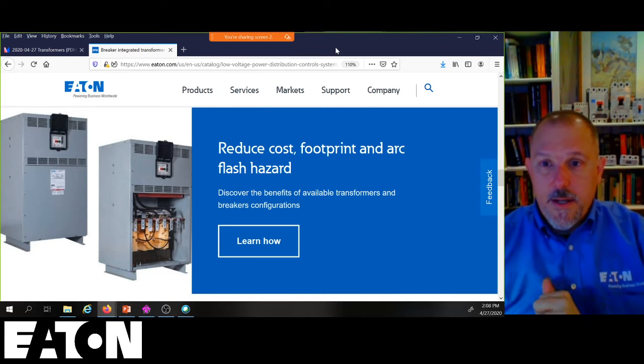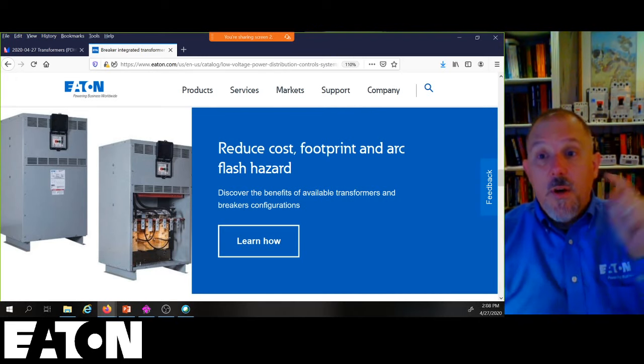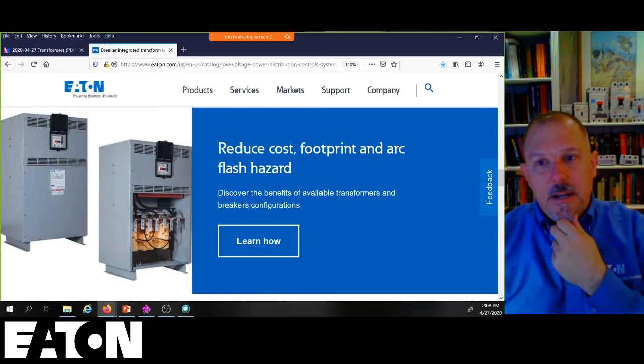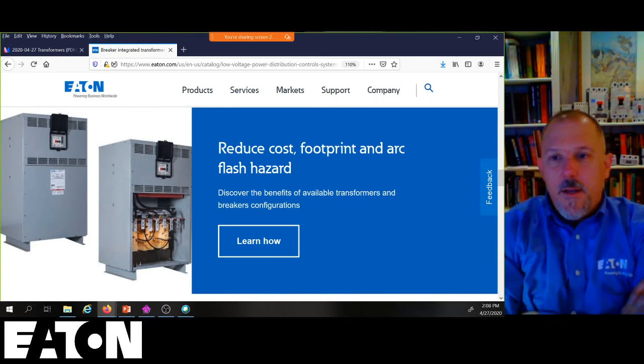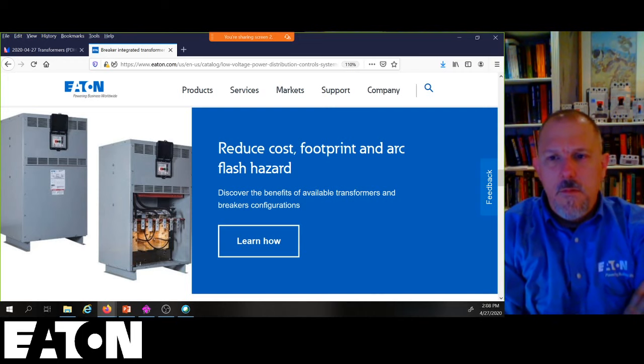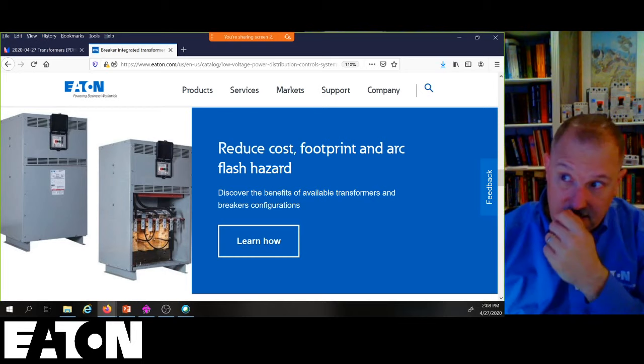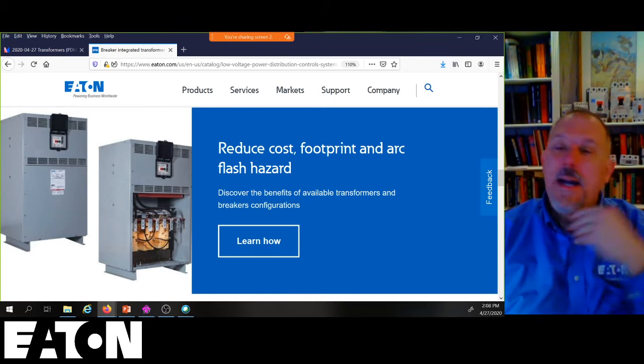Very cool little product. And again, smaller wires on the secondary, I never thought about that, Ryan. That's a good point. So Ryan Jackson is saying that the integrated overcurrent protected device, the BIT, will allow smaller wires on the secondary, since we need not worry about 240.4(B), the next size up, being disallowed. Interesting. I like it. I've got to put that example in there too.